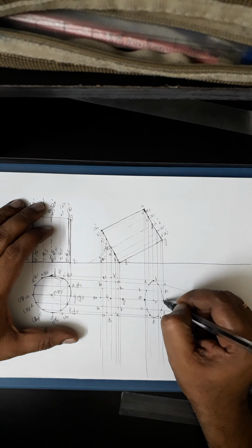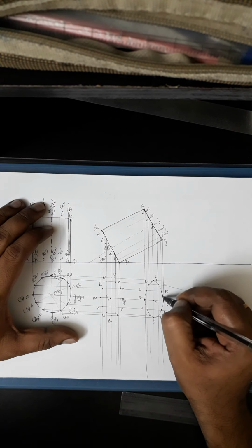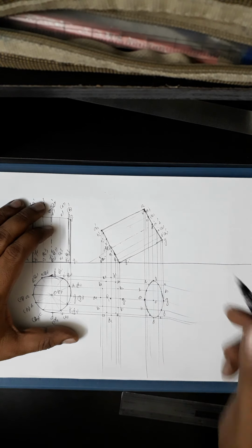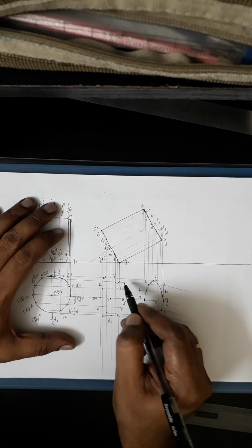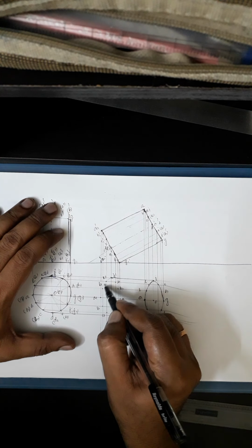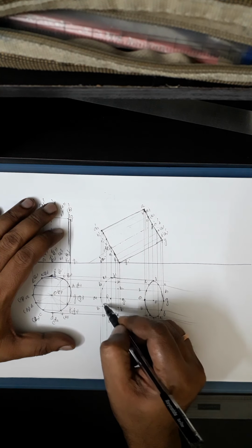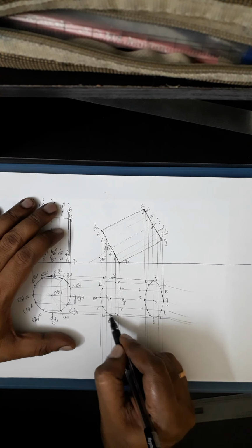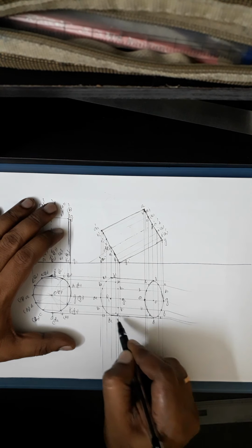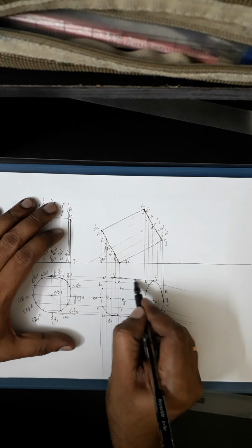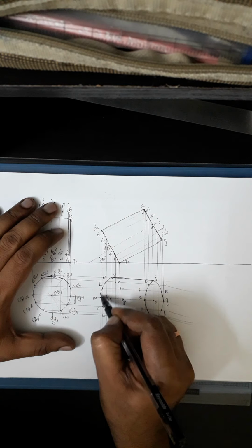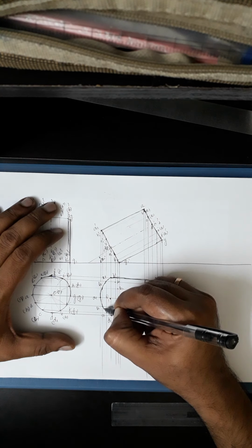Otherwise, it is very difficult to draw a very smooth curve. That's why the minimum number of points to be taken on the circumference should be 12 points. Then you go for this outermost edge. Instead you can draw the outermost boundary of the curve. When it comes here, it goes like this. The outermost end generator should go tangential to this. So this is the outermost boundary. That will be a dark line.